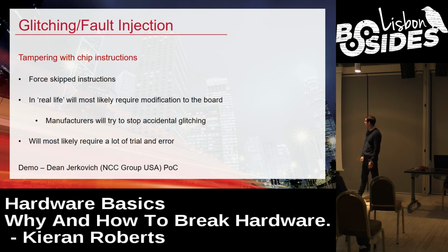So glitching or fault injection, same thing, depending on who you speak to, who you learned it from. We're going to tamper with the chip, potentially force skipped instructions. This technique can also be used to zero out registers and things like that with very precise EM. That's high-end stuff, but you can kind of make this work on a budget.